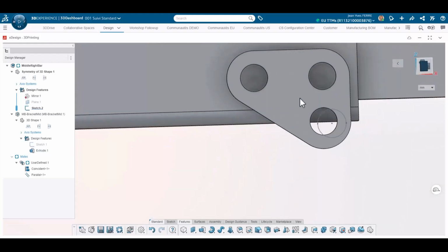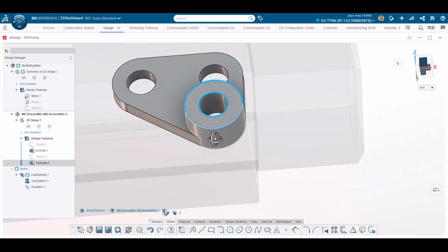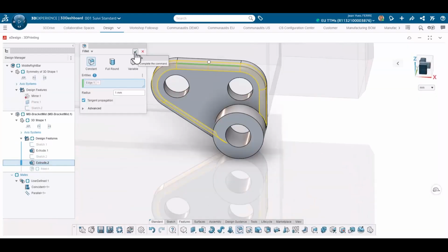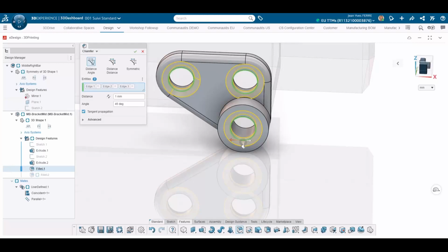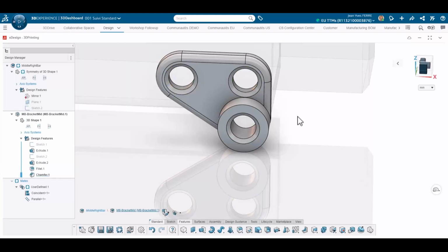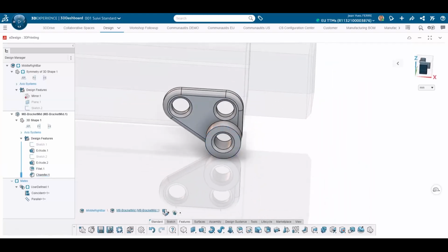Again, I create a 2.5 mm extrusion for the main body. I add mates to position the part correctly with the mounting hole. This will help positioning holes on the bar. I continue with a boss of the remaining 2.5 mm to serve as a mounting hole for the motherboard.